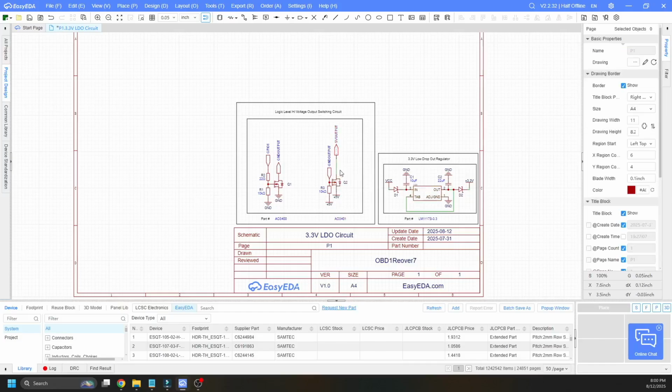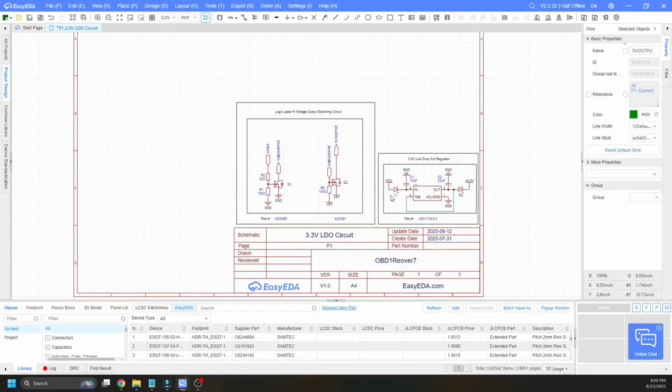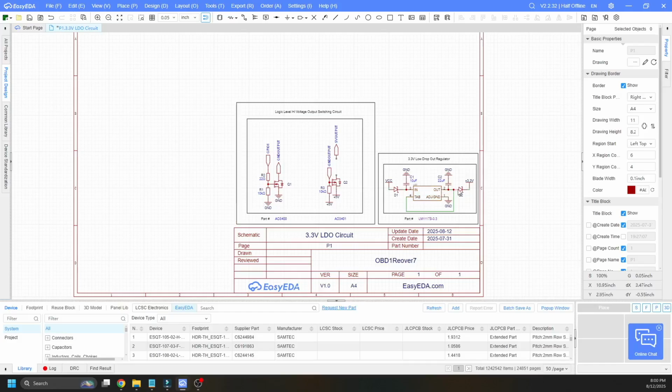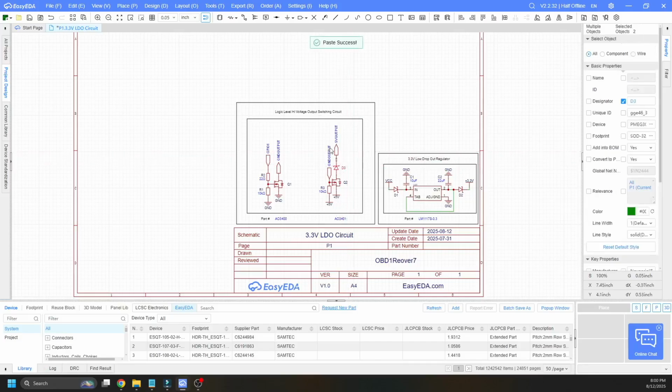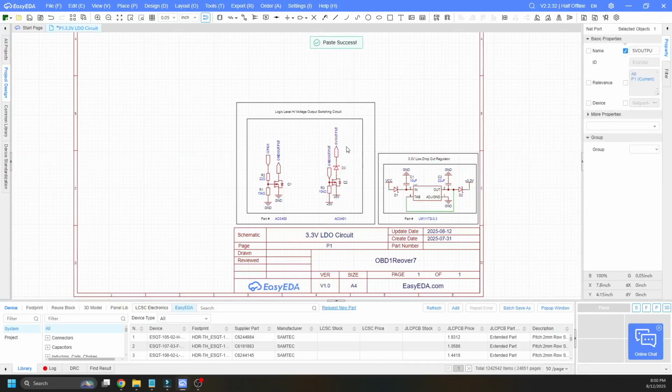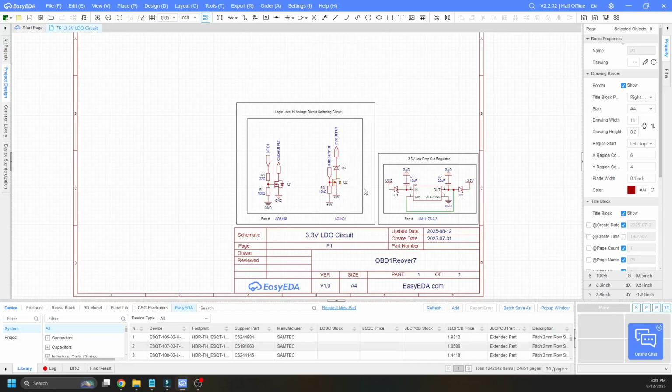And then I'm going to actually just go ahead and delete this wire, this green part. They're called wires. And I'm going to grab one of my diodes that I like to use. I'm going to copy that guy and drop it in right here. Connect my port. Okay, now why did I do this? This is going to allow the voltage to flow out in one direction, and it's not going to flow back in. So a little bit of protection now in the circuit there.